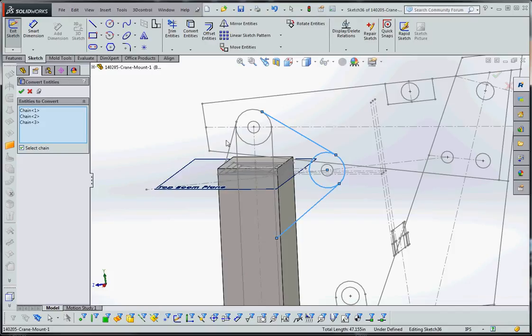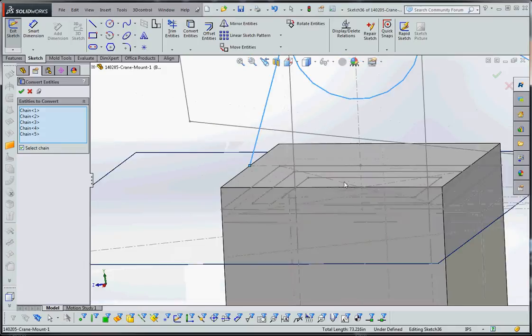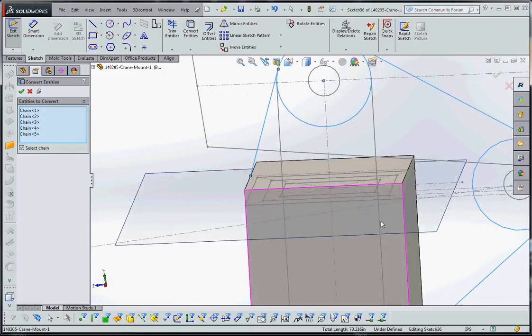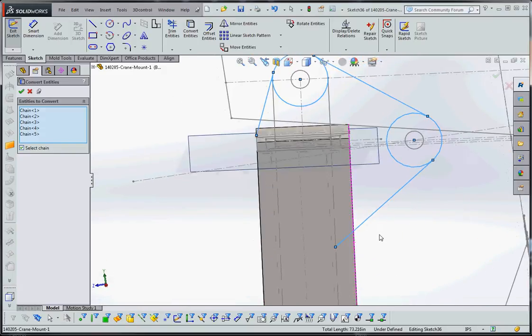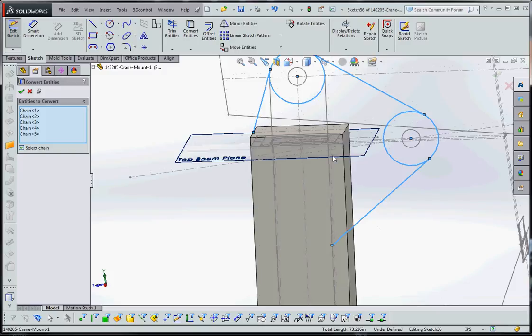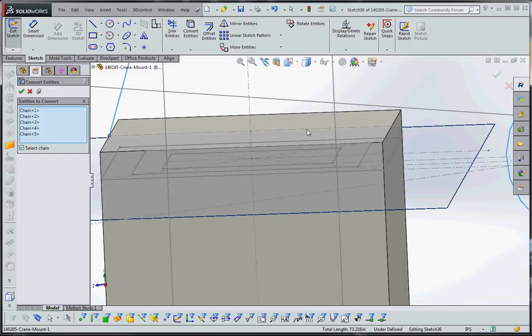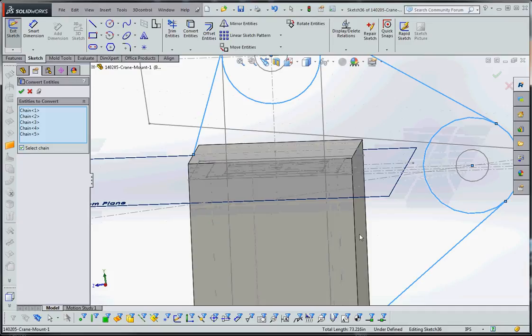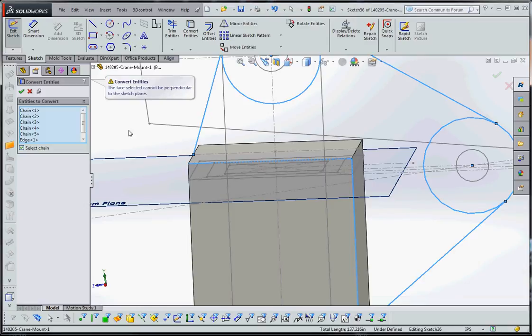Maybe not everything we need, and maybe it's going to give us more than what we really need, but what we want to do is click on these sketch elements up here in order to provide us with some enclosed geometry. Now we're not going to be able to select this center line geometry, these construction lines in the background, but what we can do is borrow from the model that's already been built and click on these edges over here. Oop, not that one, but that edge.